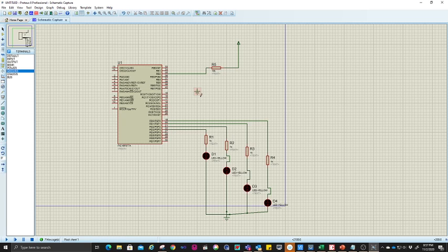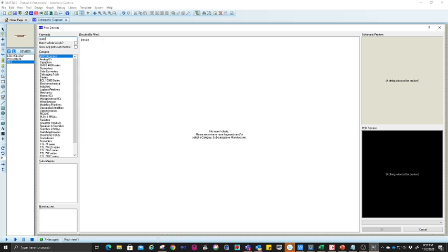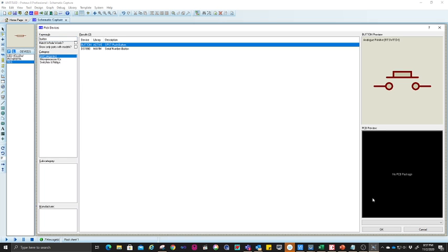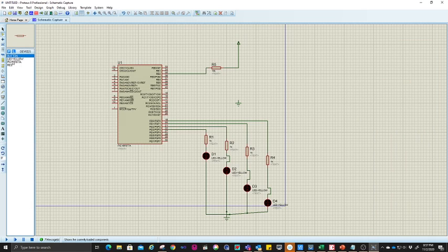So let me drop down. So here, then you must have a switch here. Okay, let's try to draw a switch here. I always use a button, which is a button switch. Cool, let's try here, button. Okay, when you press this button, the value for the input here will be 0 because this is like a short circuit.